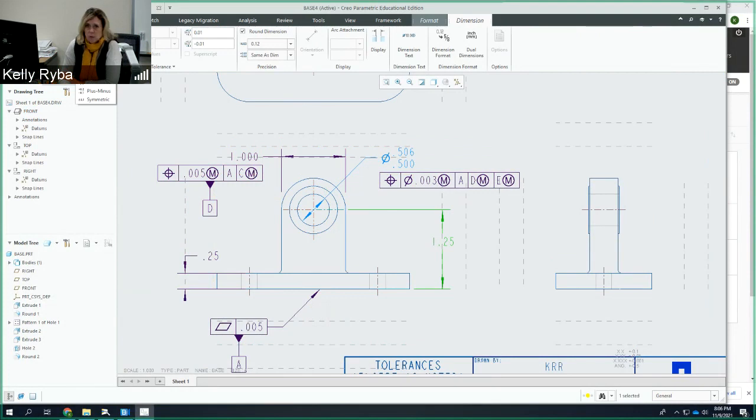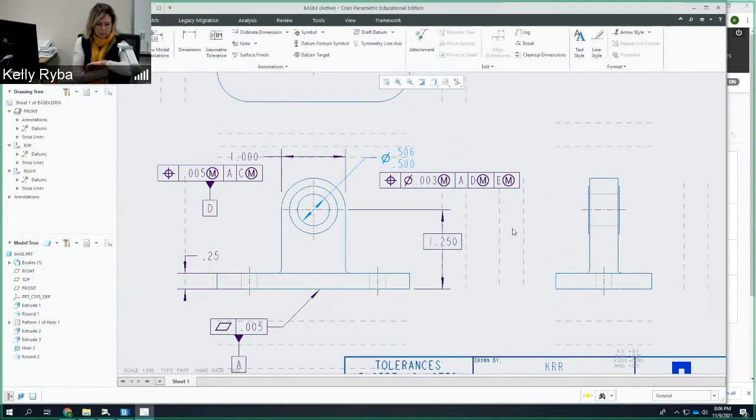I want a box around it. Okay. So it's basic, and I need it to be 3 decimal places. So right here underneath the precision, this is where my decimal places are, okay? So I'm gonna do 3 decimal places here, and it looks good, okay? It's all set for me, and I'm gonna left click anywhere outside of there.